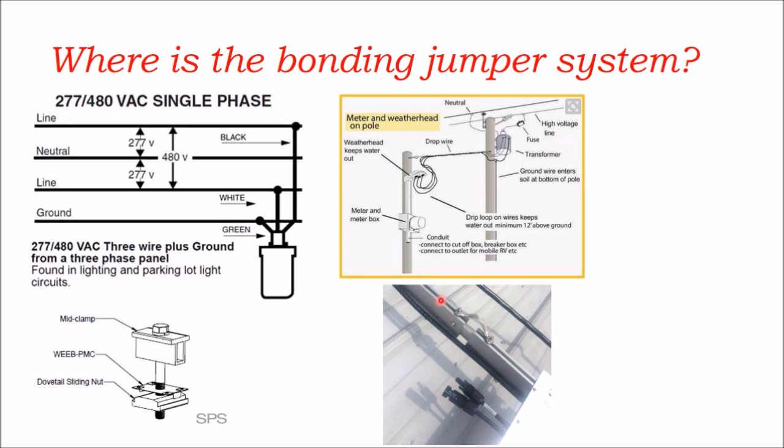Here's where you might have a connection between two pieces of metal on your racking system. And we have an anodized stick of rail and another anodized stick of rail. And even though they might be butted up together, metal touching metal, it's not considered grounded. This is a metal roof. We have a metal attachment point. But if we don't use a metal grounding screw, it's not considered grounded. And in fact, we don't even need to ground it because what we're doing is grounding the railing above it. It's probably better if we don't ground the footing. We make sure that our ground path goes from our rails directly into our equipment ground conductor.